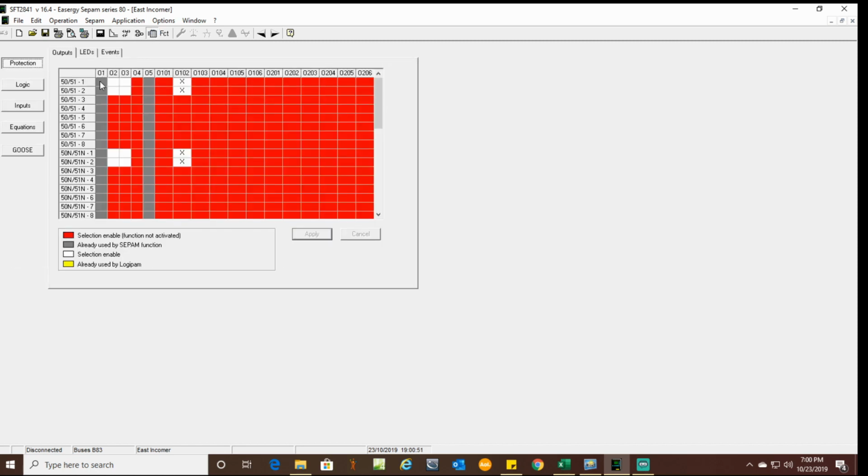Here, in addition to our protection of 50/51, wherever we trip a breaker, that's naturally going to trigger O1 because that's by default, that trips your breaker. We're also going to be in output 102 because that light's a remote pilot light, but we only want to light those on an actual trip. Here, like with 27 and 59, that's not intended to trip the breaker, so we will not have that energize that light, but with our high frequency, we would.